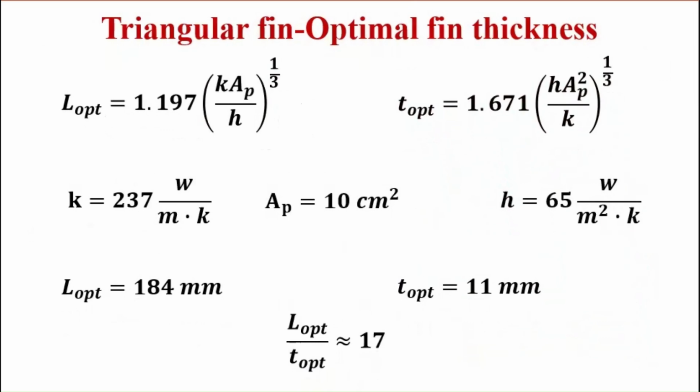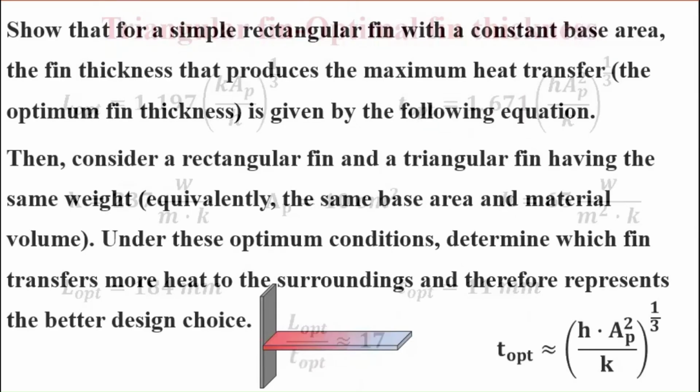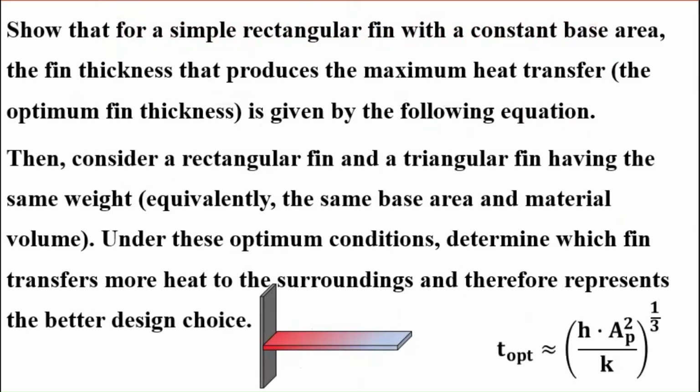Thermal management systems, particularly in electronic devices, require continuous reductions in size and weight in order to improve overall performance. The performance of a fin thermal system is determined by a combination of several factors, including the geometric shape and optimal dimensions of the fins, their weight, the pressure drop associated with fluid flow, and the arrangement of the fins relative to the wall and the surrounding components. All of these factors must be considered together in an effective thermal design.